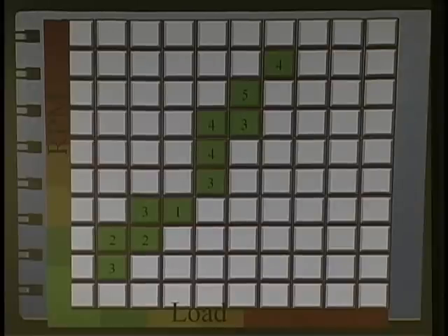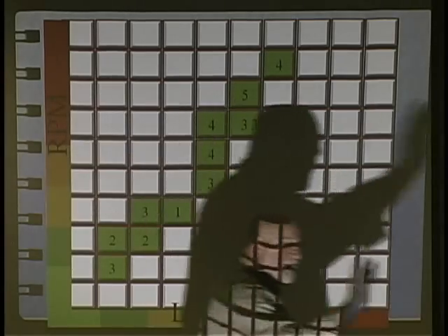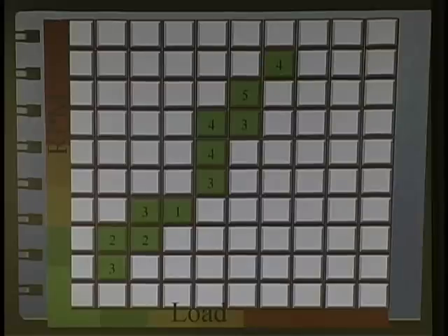If you have an E-scan, you see this. If you don't have an E-scan, how are you going to see every fuel cell? You got to graph long-term fuel trim and then drive the car through the fuel cells. You got to start out, and don't be whacking the throttle, smoking the tires, you know. So what you got to do is drive the car normally to heavy load and then back down again, and then fill the squares on his computer. What you're going to look at is graphing, and then you can bring your playback frame back, and see what the actual long-term value is in any given cell.